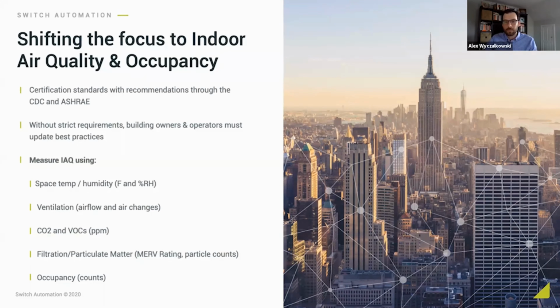So we're taking these guidelines, comparing them to the data that we have and determining whether our indoor air quality is good. If it's not good, if it's bad, then we need to take some measures, do things like increasing ventilation, filtration, humidity. So we know that's where we're starting. But before we consume all this data, we need to develop a strategy first.